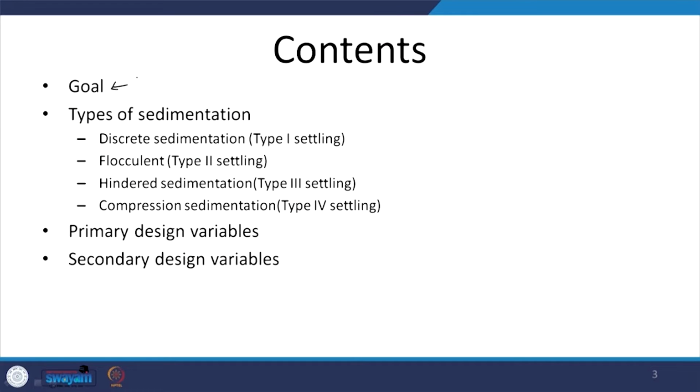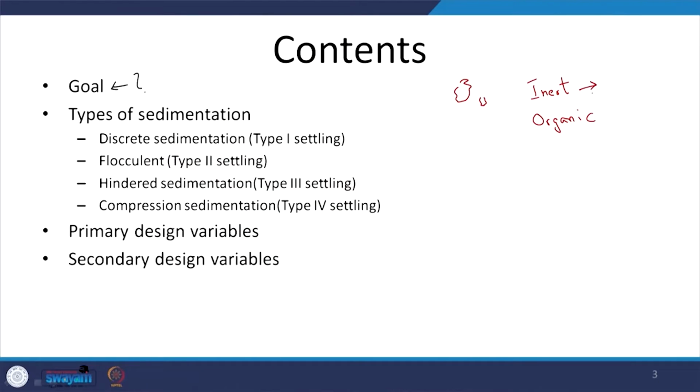So, what do I want to achieve out here, right? So, we have suspended particles, relatively bigger, some smaller, some of these are inert, some of these have organic content, right. So, inert, if you do not remove them, they will cause issues down the line in the other unit process by settling out, and you are going to have relatively lesser effective volume. Also can lead to abrasion and wear and tear of your relevant machinery. Yes, so you do not want the inert content, and typically the bigger or heavier inert content we remove during preliminary treatment or during the headworks, right.